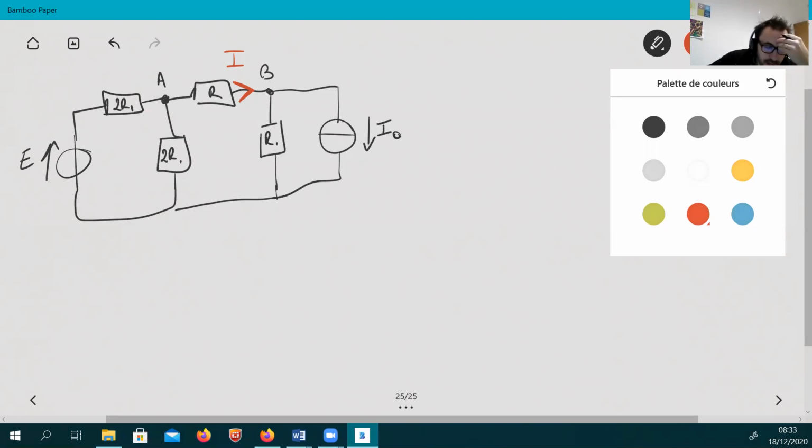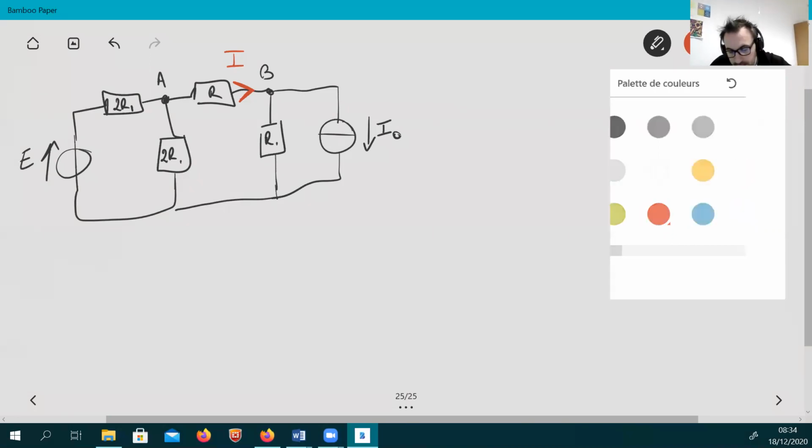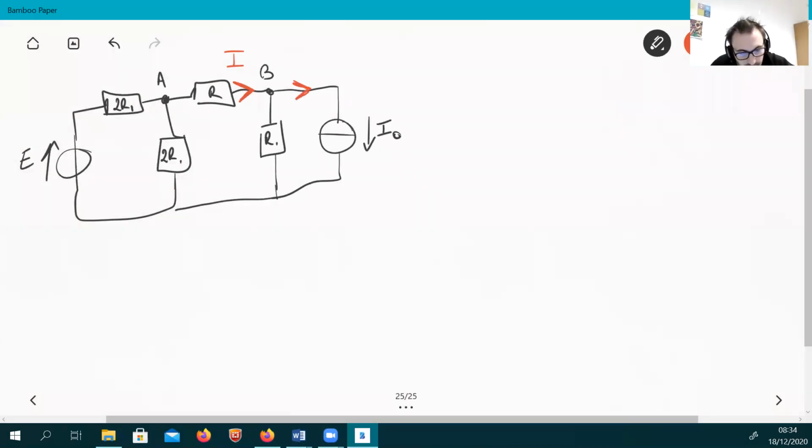As you spread the currents, you apply the node law each time you enter a node, and then you apply the right amount of mesh laws, corresponding to the amount of unknowns you have. You already have one unknown, but as you start spreading the current through the circuit, you will introduce other unknowns. So let's keep finishing the labeling.